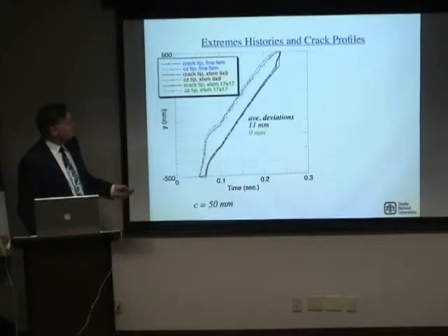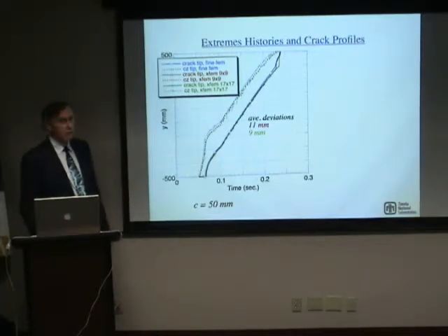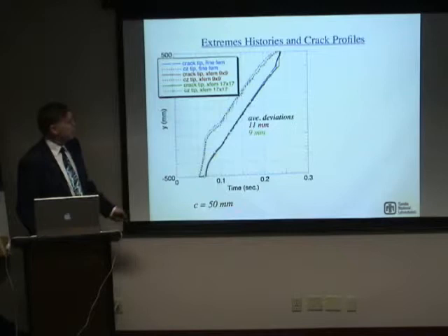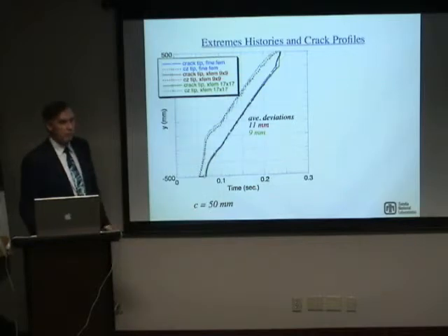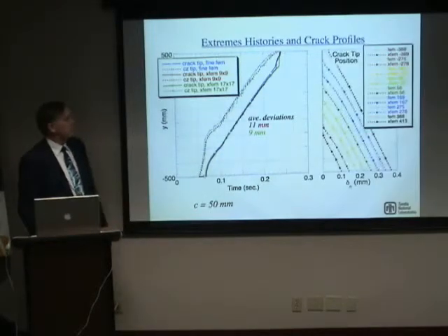Okay, now you can see improvement here. I'm running short on time, so I'm going to go through this a little quickly. But you can see improvement here. Not all of it is due to mesh refinement going 9 to 17, but also is that we have this parameter that we call C back in our analytical solution that ties to the length of the cohesive zone, and as you change this, it will change the results, which suggests that maybe in the most formal implementation of this, you would want to have this being changed by the numerical method.